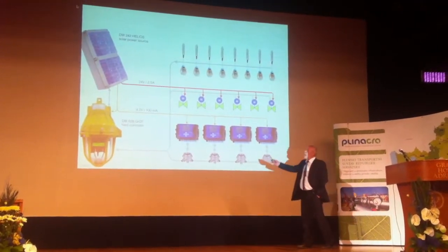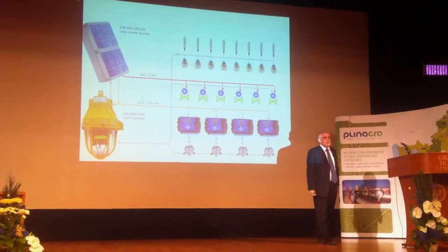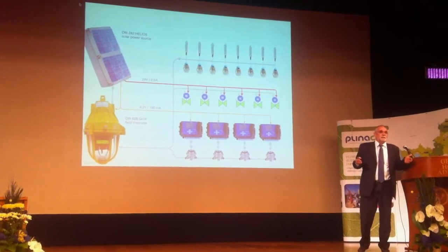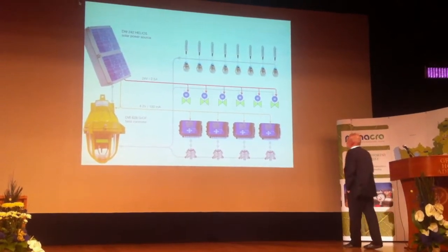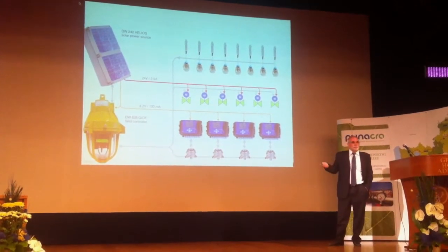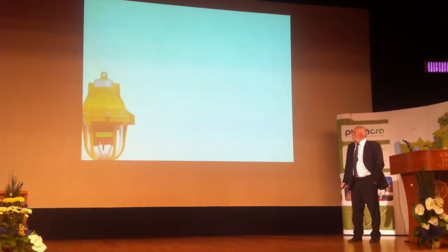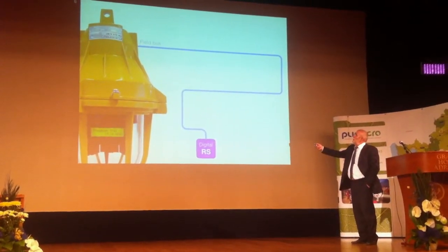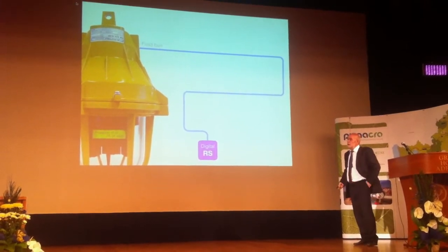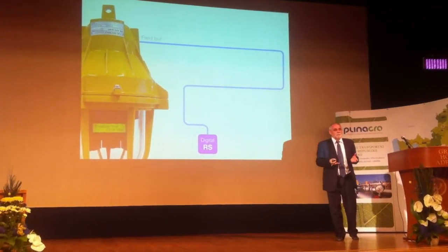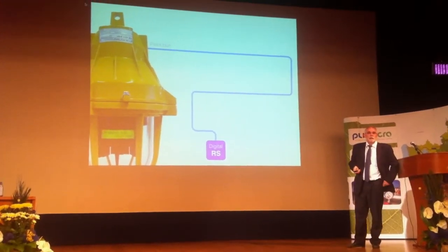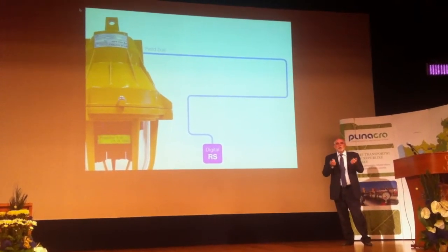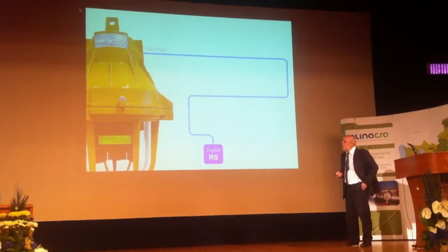If you have a large station like that, with remotely operated valves, with multi-branch skids, with many correctors, then most probably we would suggest using this device. This device was developed on the request of Gaz de France. It's one of the very few devices in the world using field bus in a battery-operated environment. We use field bus in refineries, in large companies, but field bus in a gas transfer station where you have no communication, no energy, it's quite challenging.